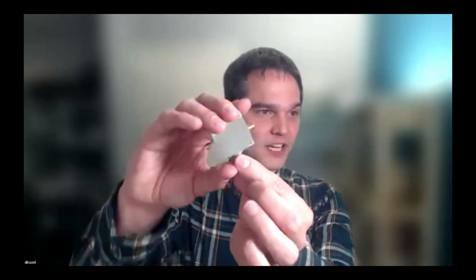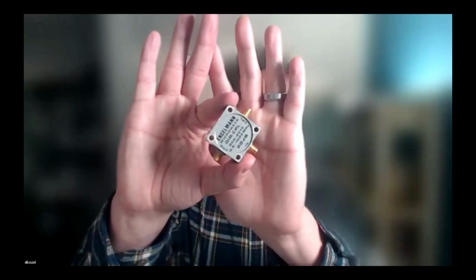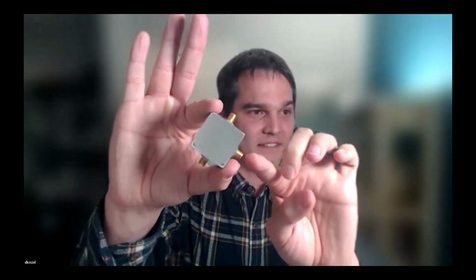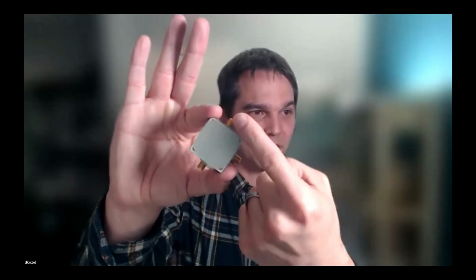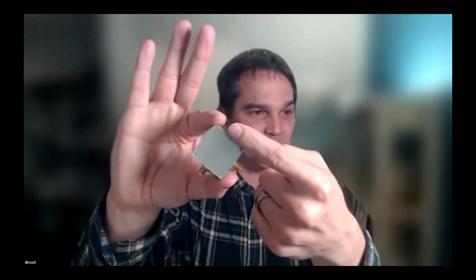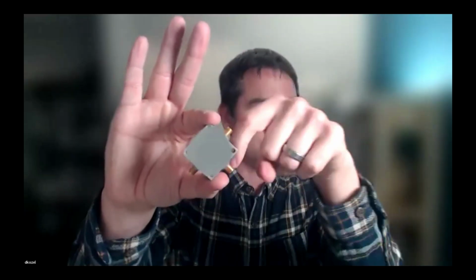So for things like directional couplers, you have 3 ports. You would just end up measuring your input port to your output port as one set of measurements. Then you would measure potentially the reverse, swapping that around in your VNA. And then you would swap it around again to get your input to your coupled port, and then your coupled to your output port, to get the full piece. Each 3-port combination.